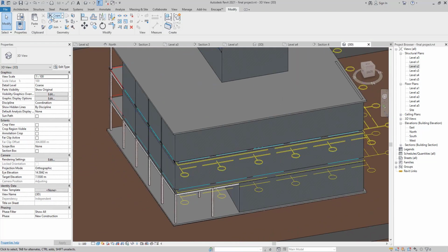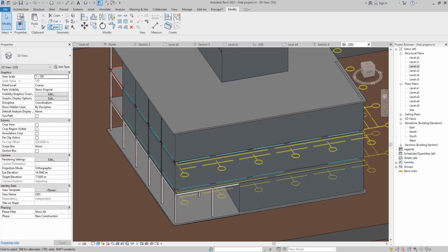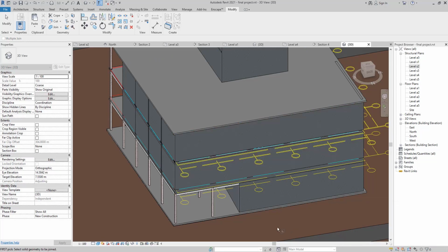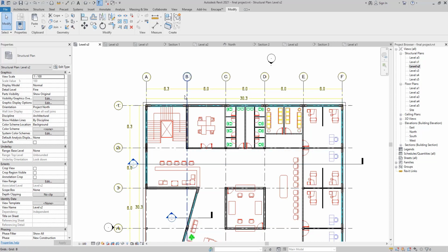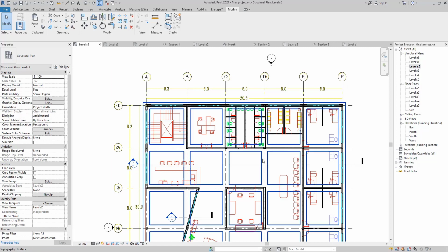So it looks fine. We just need to go to the architect modify tab, try to join our walls with each other, unjoin elements. It's alright. We just go to S2 here again, and after that we need to create one more section line because we already fixed these two walls.